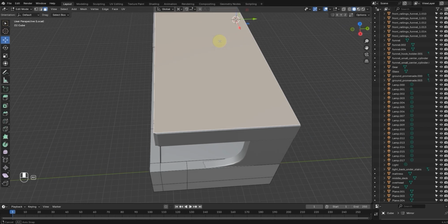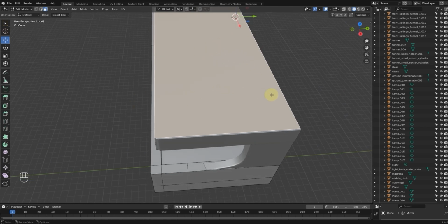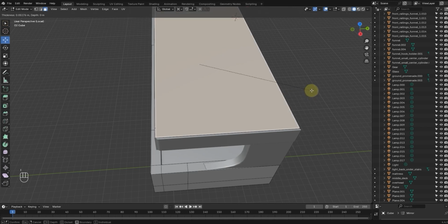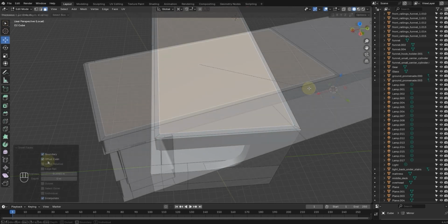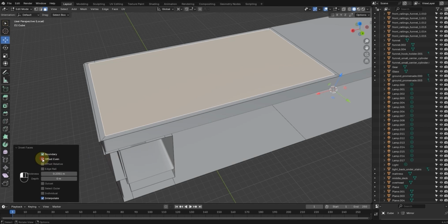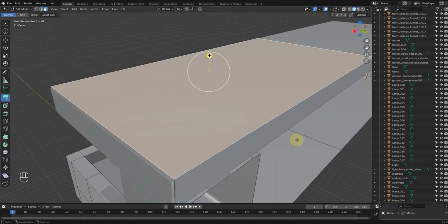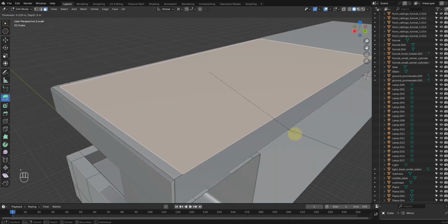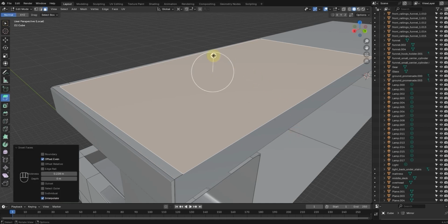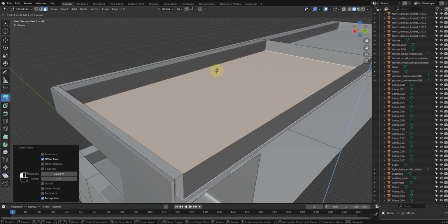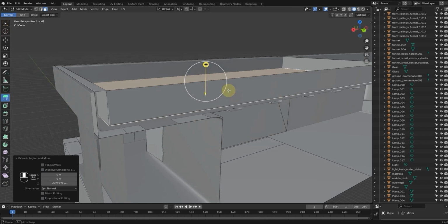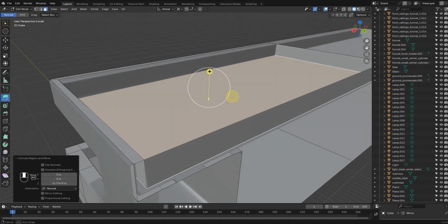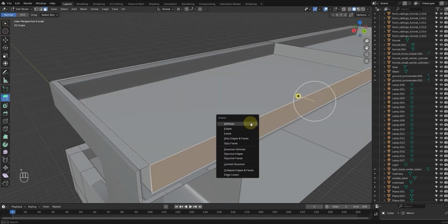Then I can press I on the keyboard and then bring it in, just to sort of create that inner wall for the balcony, for the upper balcony. So I'm going to select uncheck boundary here, because it's when you disable boundary. So with the boundary unchecked, I'm just going to pull it down, and then need to delete faces.